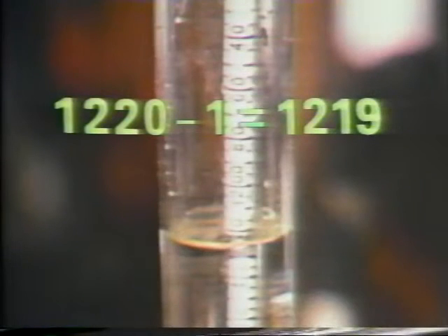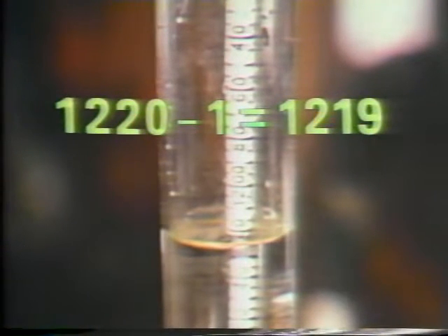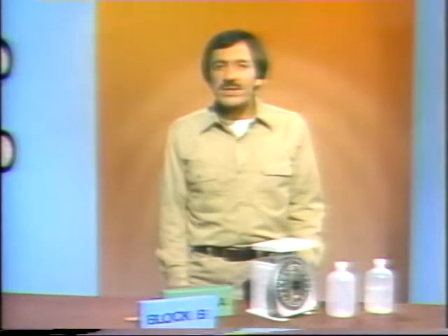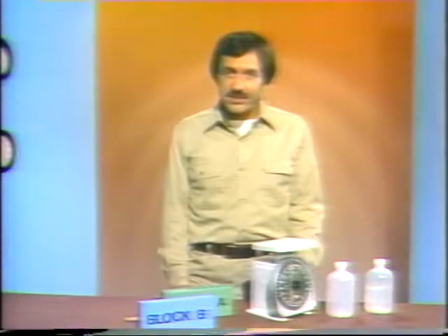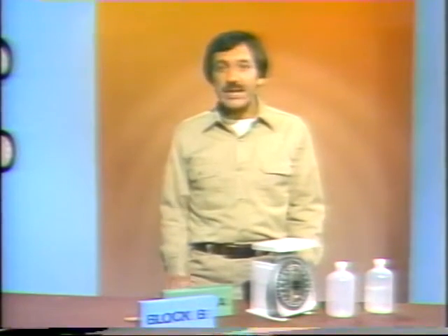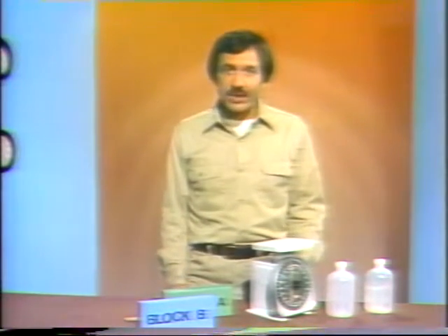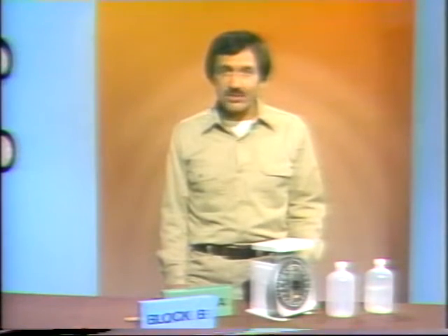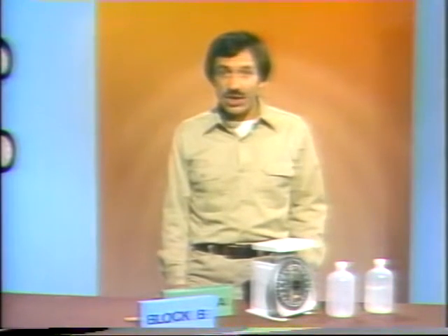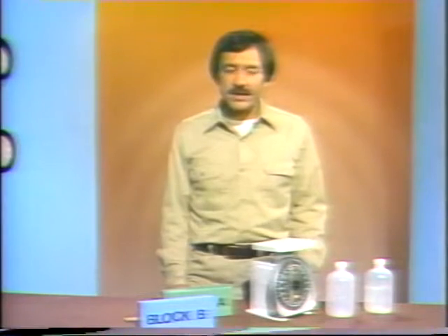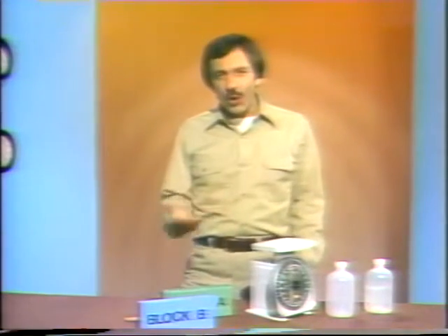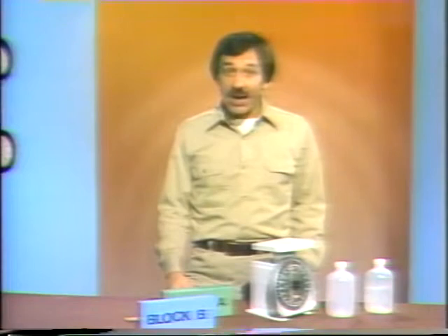A reading of 1,220 with a -1 correction factor gives us a corrected reading of 1,219. All of the readings for individual cells are corrected in this manner. For a typical lead-acid battery, if the corrected readings are all above 1,200, this indicates there is a good charge on the battery.